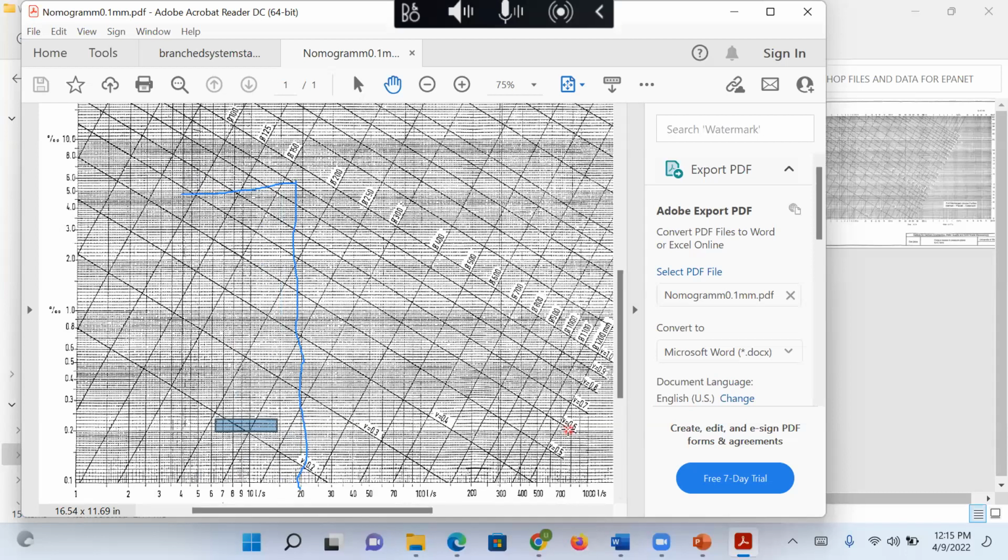Look at it. So the velocity at that point is 0.6, while the pipe size is 100. Those are the two parameters you need. What is the velocity? Because you don't want the velocity to be lower than a certain value, and you don't want the pipe size to be inadequate. So that's how to define the pipe size. Next week, we're going to do more and design more.